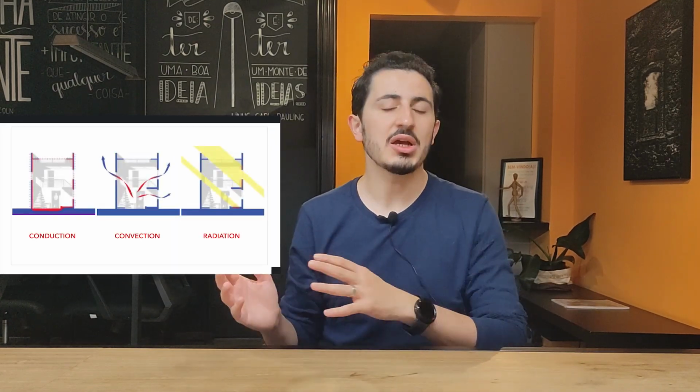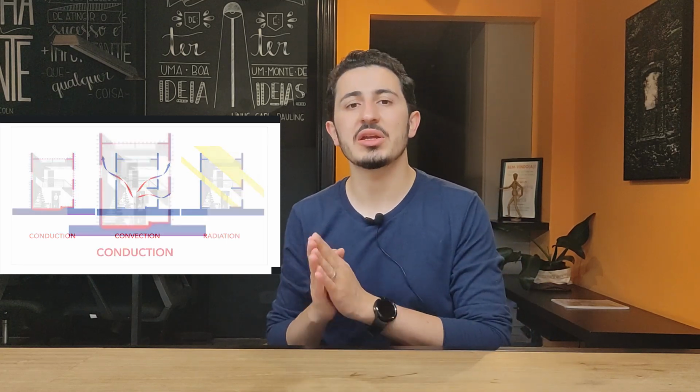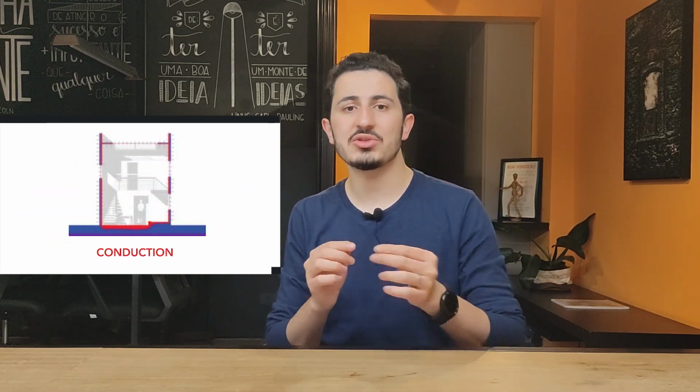So the walls and the roof are in contact with the exterior air, and the foundation, of course, is in contact with the soil. This building envelope is basically the barrier between the interior and the exterior of the building, which helps us maintain our main goal, which is conservation of the interior comfort temperature. As we explained earlier, energy transfers in different ways, and the most important way in buildings is conduction, the heat transfer through the envelope's solid material. This is why when we take good care of our building envelope, we can achieve better energy conservation inside and limit our heat loss.